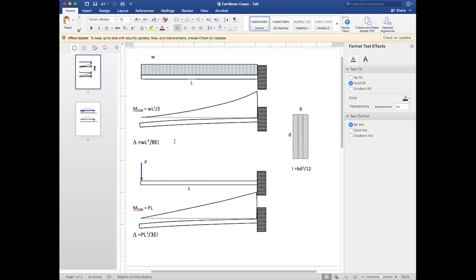They just cut the bottom. So they took a chalk line, strung it across the LVLs, and then took a saw and cut them. Absolutely the wrong thing to do. The proper thing to do in a case like this was to remove how they were put into the wall and turn them upside down.